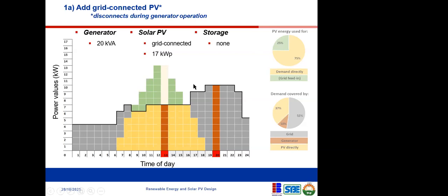So now what happened is this. You're connected to the grid, but once the grid fails, your solar system stops working. So you have a grid-tied inverter. Remember when I said that your grid-tied inverter should have the capacity to know when the grid has failed and it will knock off supply to the grid. It will not push power to the grid. That is what is happening here. The grid has failed and your inverter knocks off supply.